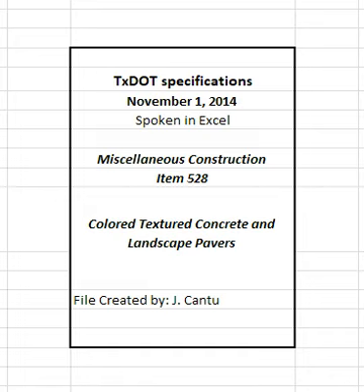Place dies with a repetitive pattern on the concrete surface and hand tamp to create the required texture or imprint shown on the plans. Use a brick pattern if no texture is specified. Apply colored curing and finishing compound in accordance with the manufacturer's directions. 3.2 Landscape pavers.